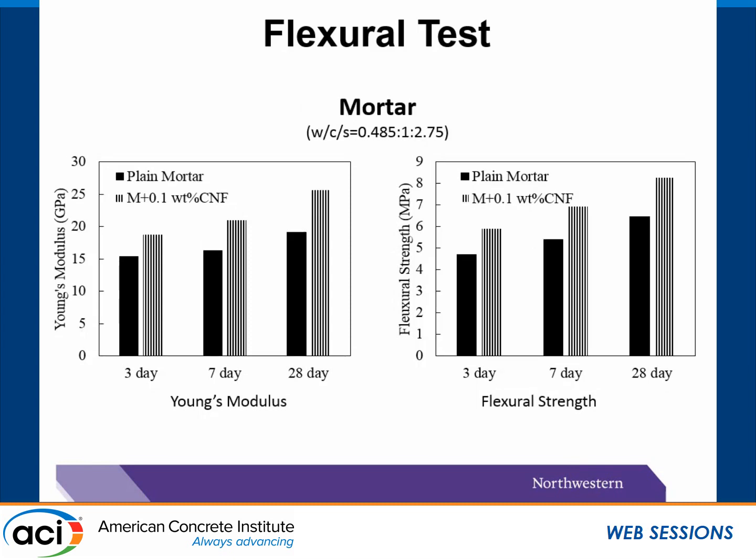Then the same dosage of CNF is added in mortar. The results show the modulus of elasticity is increased from 19 gigapascal to 26 gigapascal at 28 days of age, and the flexural strength is increased from 6.5 megapascal to 8.3 megapascal at 28 days of age.